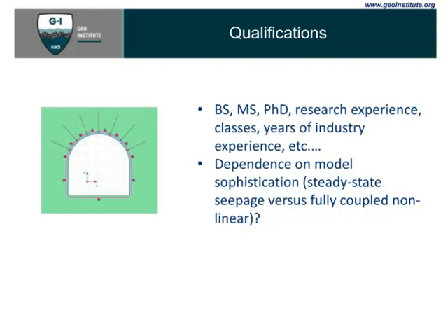And then there's really the whole separate aspect of constitutive modeling, which is a core component of geotechnical analysis: understanding the advantages and limitations of using a Mohr-Coulomb model versus, say, a modified Cam-Clay model, depending on what you're trying to model. So if you want a good chance of getting good quality results out of your numerical modeling, who should really be running these models, who should be reviewing them? It probably depends a lot on what kind of model you're running, anywhere from simple steady-state seepage analyses to very complicated numerical models.